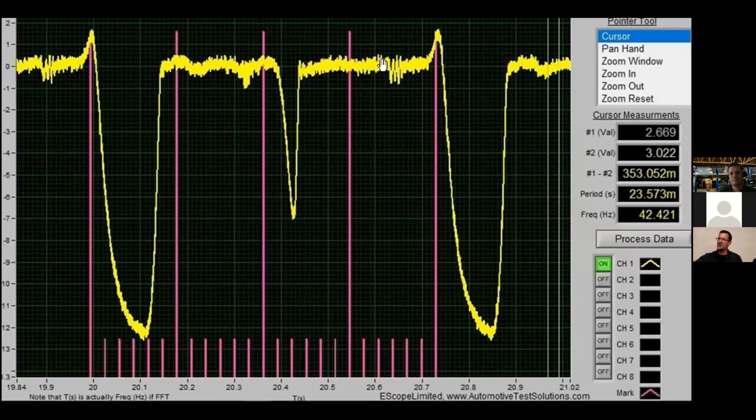So let's think about this for a moment. This represents 180 degrees of crankshaft rotation. This would be 90 degrees. Halfway between that and the bottom is about 45. Right? Halfway between here and 90 is about 60. So here is where we are supposed to close the intake valve. And we have this much stroke, about 120 degrees, to capitalize and build compression.